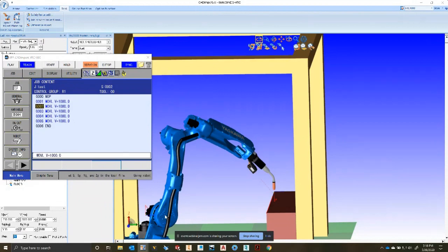Okay. Josh asks, can you add a 7th axis linear rail? Yes. That's where I showed you how to import a CAD model and how to set up a controller. There was a button on the right-hand side for advanced; that's what you would click to initialize it. And there you would set up your rail. You will need to have all the mechanical specs for that rail, because if you don't, it won't know how far it can go, or how fast to accelerate and decelerate. You'll have to know all that ahead of time. But yes, you can definitely do that.